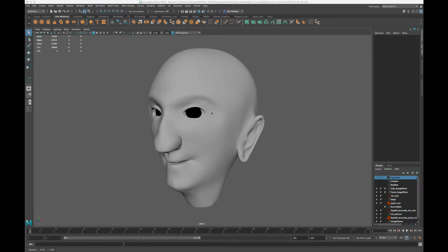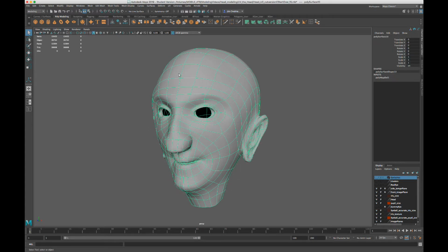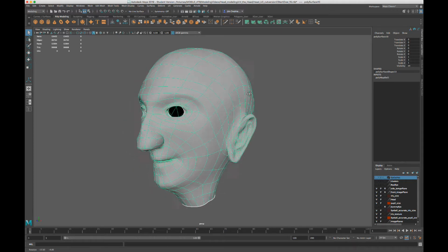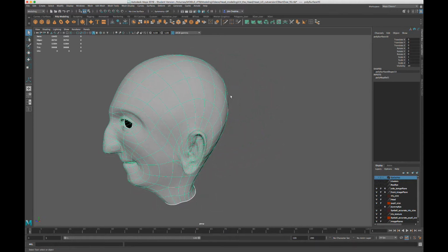Okay, this next video is mainly going to be focused on UV setup, creating UVs, using cuts with the UV toolkit, and unfolding them in the UV editor. It likely could be one of the most tedious parts of the project before you start painting on it because you might be eager to do so. Yet in our classic workflow here, it's essential that we do set those up and get on with it. So I'm going to show you a pretty simple way to approach it and also note some of the pitfalls and errors that can happen along the way.